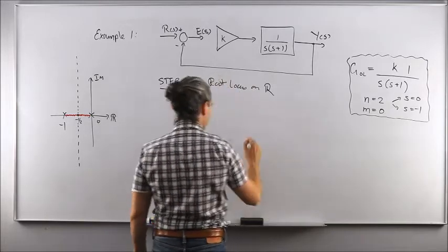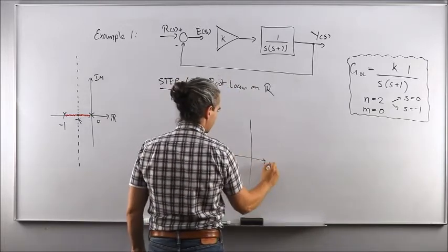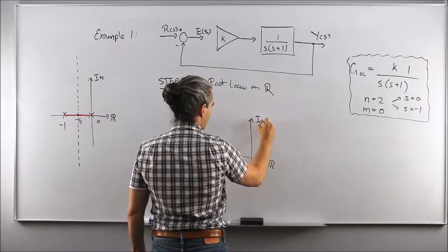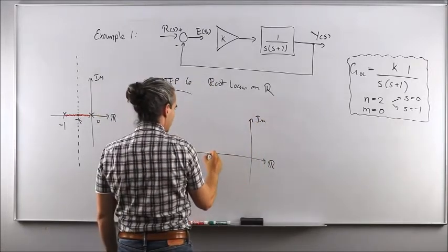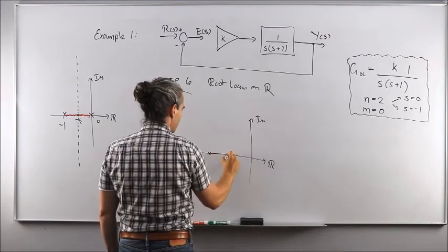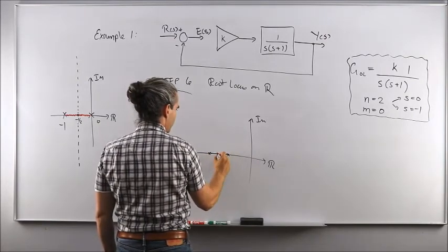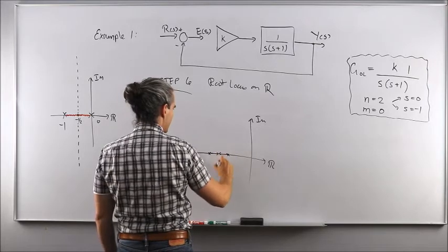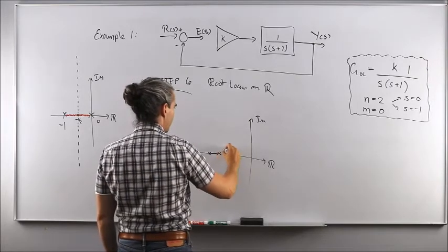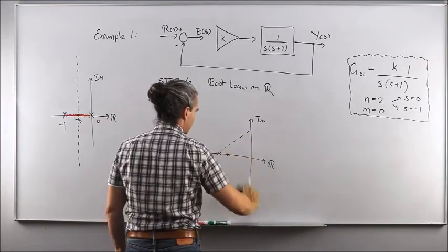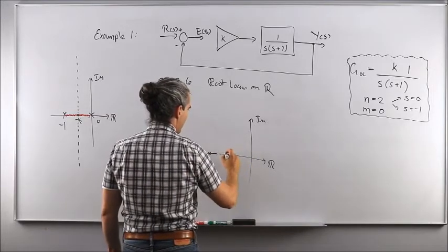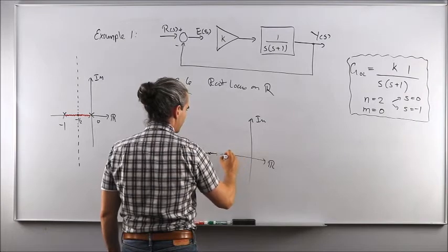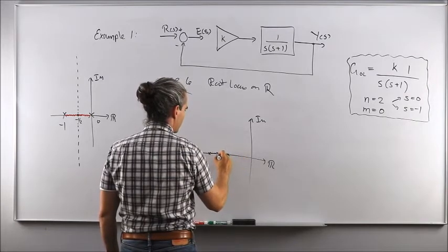If you end up with a complex root locus with a bunch of poles and zeros all over the place, sometimes two poles would fly towards each other, meet up, and then instead of flying up and down, they would want to fly along asymptotes that may have an intersection different than where those two poles meet on the real axis.